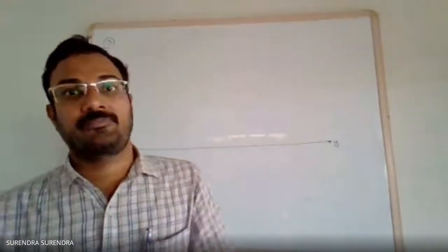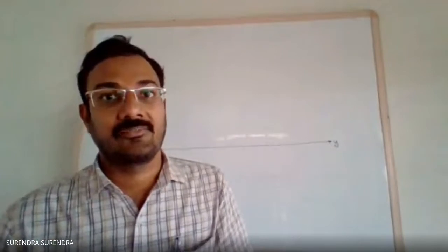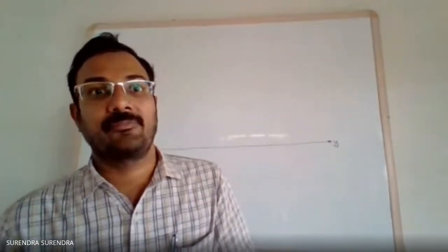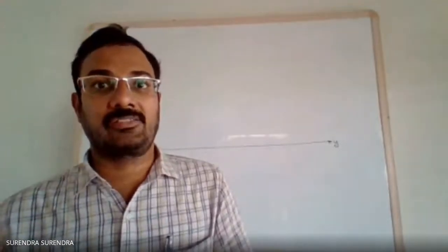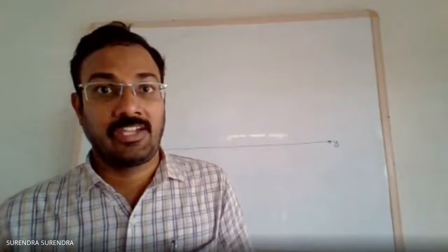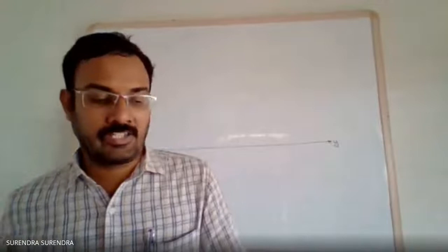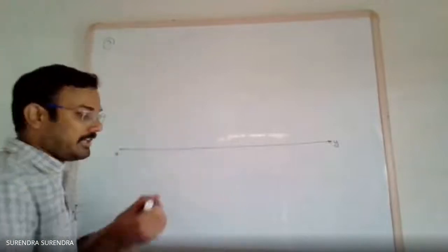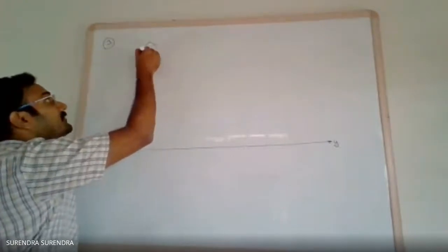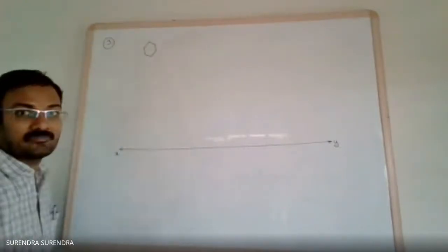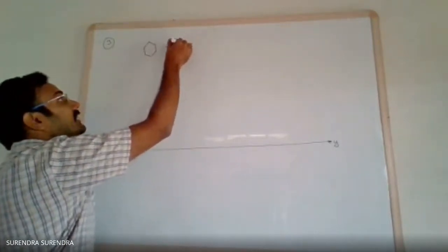Now, in this problem, we are starting the problem with front view, and it is given as a corner on HP. So, no need to draw the side perpendicular to XY line. Especially for hexagon, you must draw it with two of its sides parallel to HP. So, to draw the hexagon, there are two options. We can draw the initial view in this orientation, or we can also draw the hexagon in this orientation.